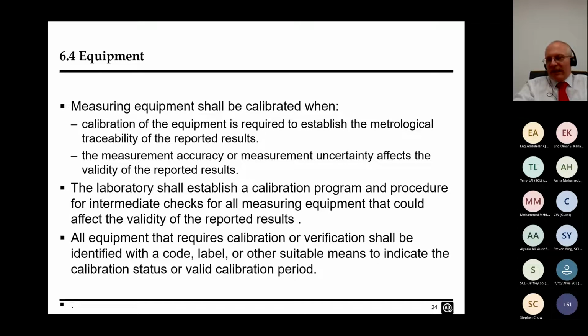Your measuring equipment needs to be calibrated, but it only needs to be calibrated when it's required for one of two things. Either we're establishing the metrological traceability of the reported results. So the standard you're using has to be calibrated and it has to be traceable.